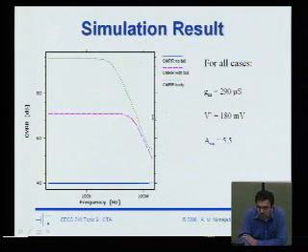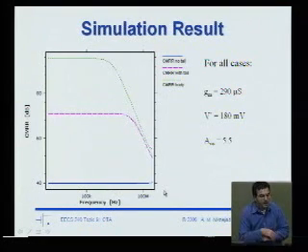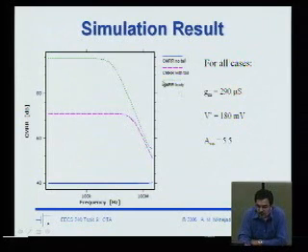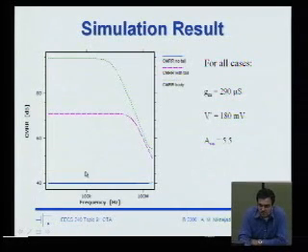So again, you had about a 1% mismatch, and so you got 40 dB right off the bat. Didn't need to do any analysis to see that. Now you add this tail current source, and you get a huge improvement, right? Wow, that's a huge improvement. So you're up to more than 70 dB of common mode rejection.